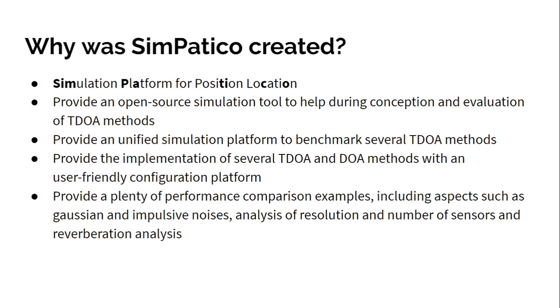We also provide a unified simulation platform to test these algorithms in different impairment models, including Gaussian and non-Gaussian model noises, and also with reverberation effects. That's not something that we have found in the literature. We also provide implementation of several TDOA and DOA methods with a user-friendly configuration platform. DOA actually means direction of arrival, so in SimPatico, we also have classical implementations of ESPRIT and MUSIC algorithms.